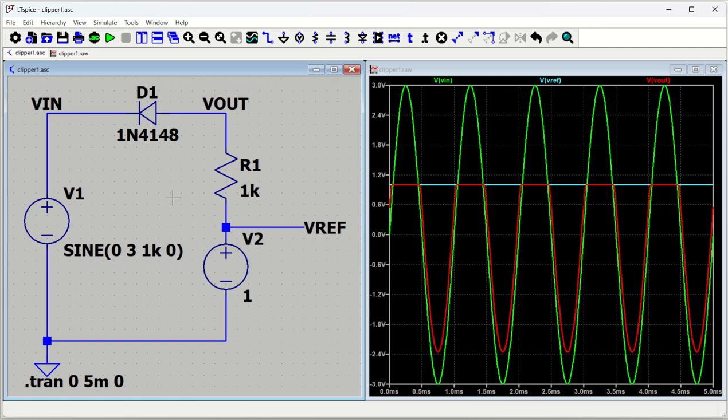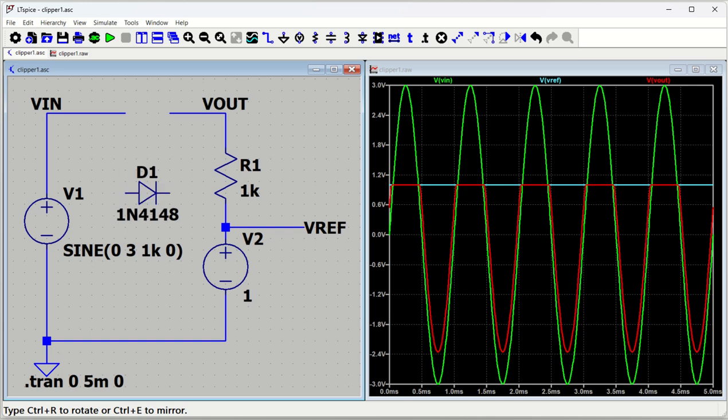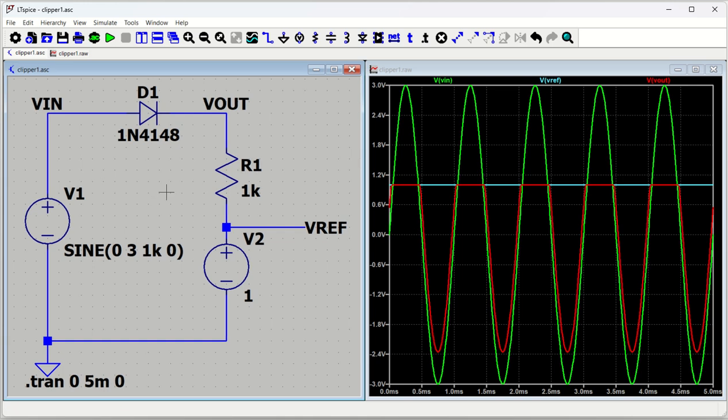Let's take another circuit where we reverse the diode and again rerun this particular circuit. So you can take a screenshot of this particular simulation, and you can do another circuit. What I'm going to change is, let's move this diode and reverse it. So if you see reverse, what will be the change that you will see, this red line will go up. Okay, and this particular reference voltage will actually shift down, right? So let's see what is happening. Actually from 0 to 1 volt there will not be any signal below. Okay, so that's the understanding.